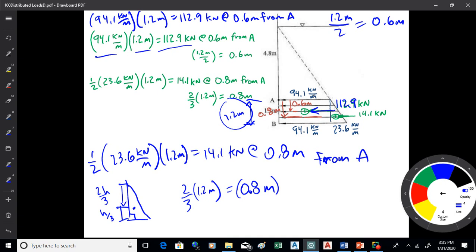Other questions on that? So splitting it in half, splitting it again. Yeah, the rectangle is pretty easy. It's in half, but for a triangle, it's a third from the base, from the right angle. Yeah, that was given. That was on Wednesday. I went over that, but yeah, that's the standard centroid for a right triangle. So if you took a cutout of a right triangle and found the balance point of it, it would be h over 3 from the right angle and b over 3 from the right angle. The balance point would be the centroid, okay? That's just a property of a right triangle, okay?